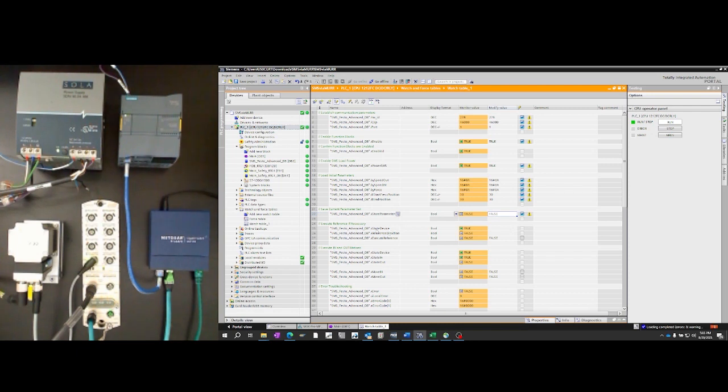Next, I'll check and make sure my state device is true. If this does not come on true, or you get a state in and state out at the same time, you may need to reference your device. You'll see in the video that it's referencing and then returning to the previous position. You'll also see from my process data that X state out changed. Now I can enter normal function. I have no errors and I can move in and move out at will.